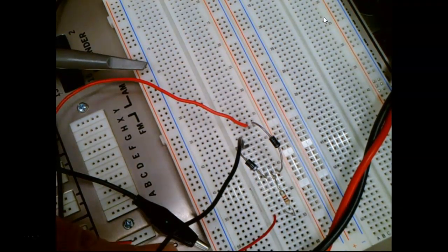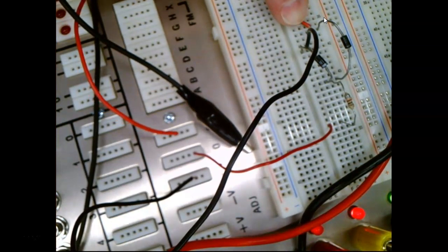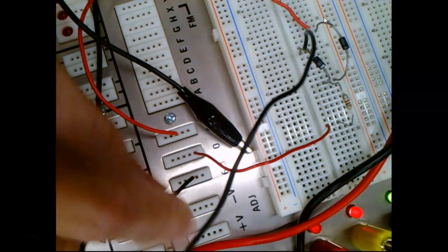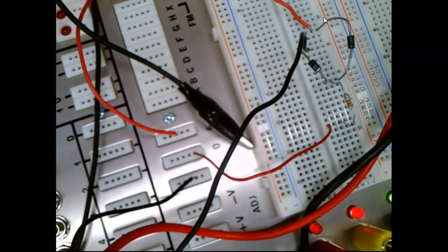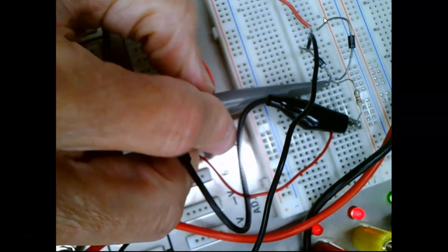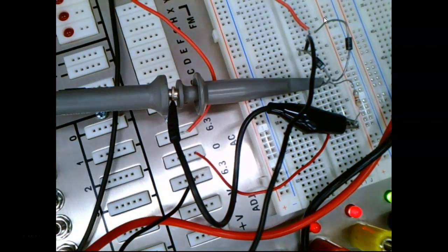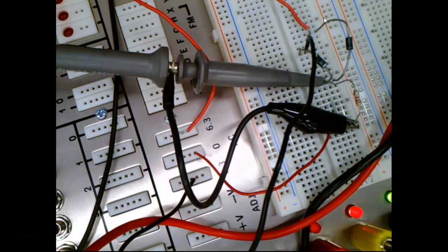So this is connected to one side of the transformer, and it's going up to one of the anodes of the diode. This is on the other side of the transformer, going up to the other anode. I have the two cathodes connected together, in the same vertical line. And then this would be what we call the common for the circuit. The common means we're going to make our measurements relative to that, right? I'm going to take ground on my scope and make sure I hook it up to the common, and now hook it up across the load. I can hook this up to any of this common line. The diodes are a little easier to do because they have a bigger lead on them and they want to stay in. The resistors have a real small lead on it, so if you hit your scope probe, it'll pull it right out of the plane.